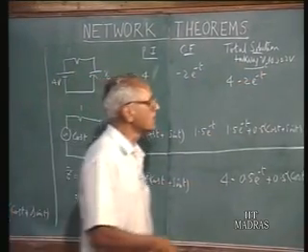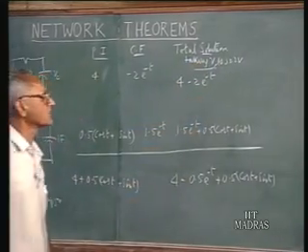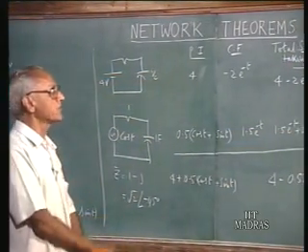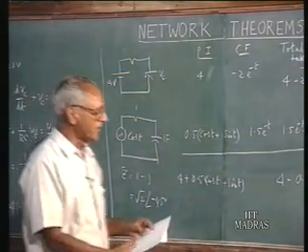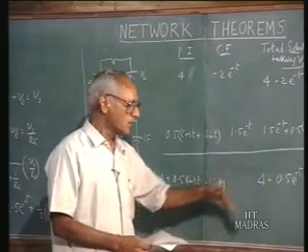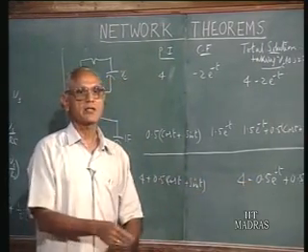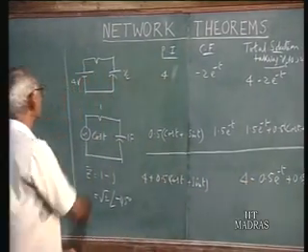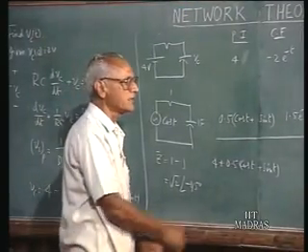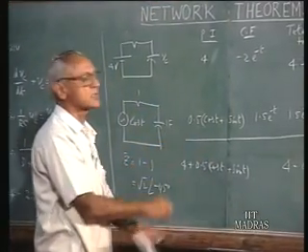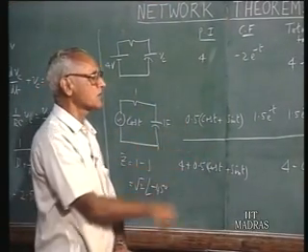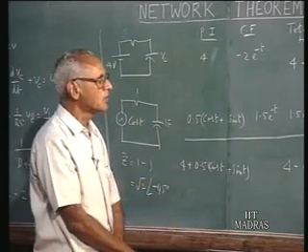On the other hand, if you take the total solution with the initial capacitor voltage to be 0 volts, you would get some value, and if you replace the initial voltage across the capacitor by an additional DC source of 2 volts, then you get the total solution correctly. So you can work that out. I will leave the details to you.